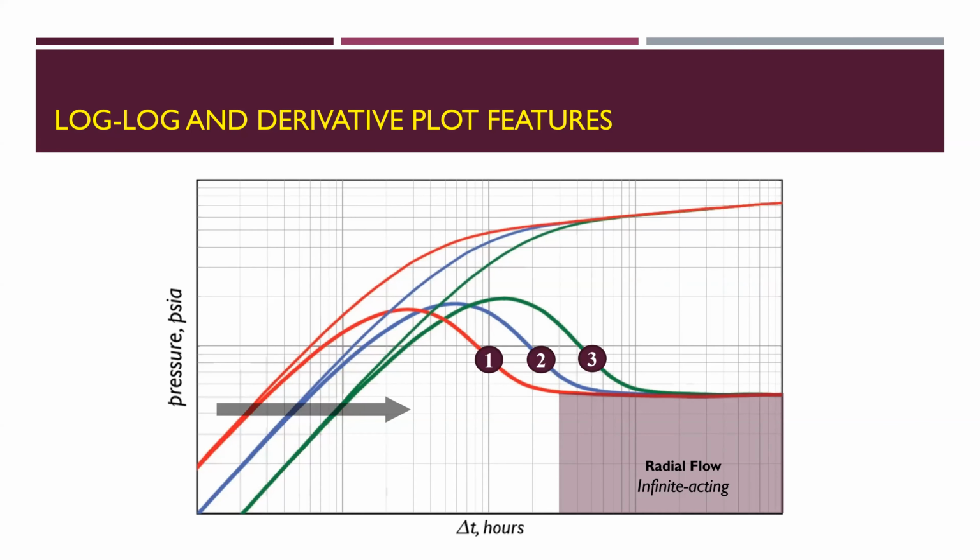So we have well 1, well 2 and well 3. It seems that the wellbore storage is increasing toward the right direction. So well 3 is exhibiting a higher wellbore storage than well 1. Saying that once you are considering a well test design for well 3, it has to be longer than the well test design duration for well number 1.